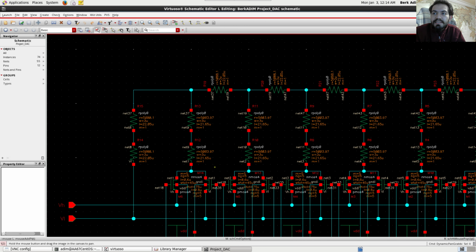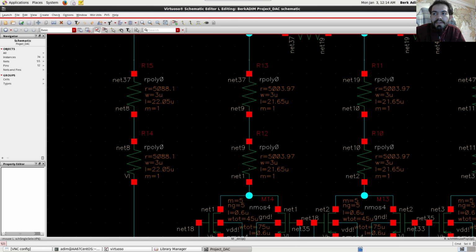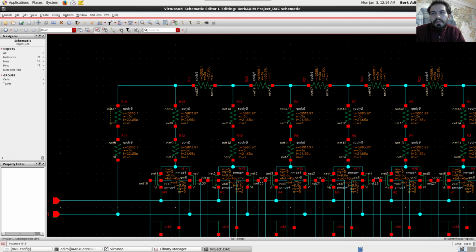We can just add the average resistance to compensate for the resistances that are not connected to transistors, and get quite nice monotonicity, because the resistances are not that large absolutely. They might be different from each other, but they can still be compensated by using an average equivalent resistance.